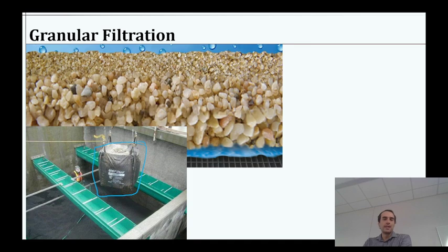So the good thing is we design these so that we reuse this media basically forever, right? It's just these tough granules. We make sure that we're keeping them there, not letting them escape. And then we can just reuse it, right? So unless we are not properly backwashing and cleaning it, then they should be reusable indefinitely. It's just sand, basically. Usually it's very carefully controlled sand grain sizes.